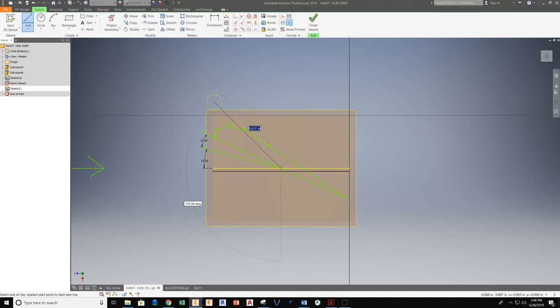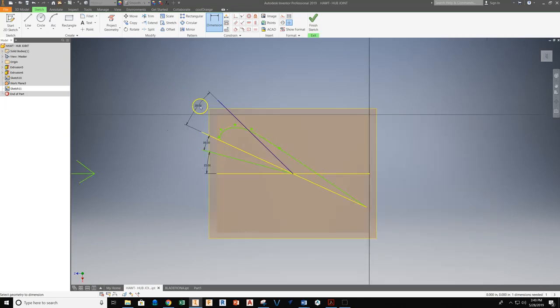And again, I'm going to draw a line, and then I'm going to utilize project geometry for the last angle, and I will then dimension from the bottom of the airfoil on the base to the airfoil angle that's going to be set out at the tip. And I'll go with that 20 degrees and set that up. Oh, come on, it's not taking it for some reason. There we go. So now we're set up here at 20 degrees.